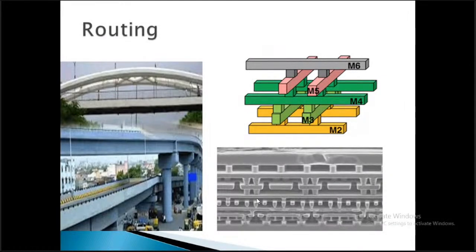Sometimes, let's say an inverter has only one metal layer. There is no need for any more connectivity. But if we are talking about a complex full adder design, at least 6 metal layers are needed. If we are taking more, like eMMC, and there are different kinds of IP, I2C, I3C, different speed blocks, SerDes, there we need at least 16, 17. So a minimum of 15, 16, 17 metal stack is needed for the connectivity. If you see, this is the chip level, how the connectivity is done.